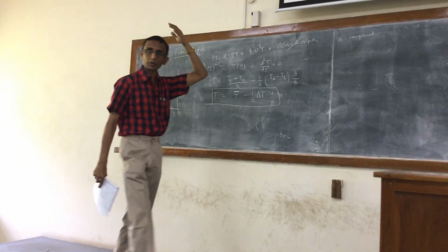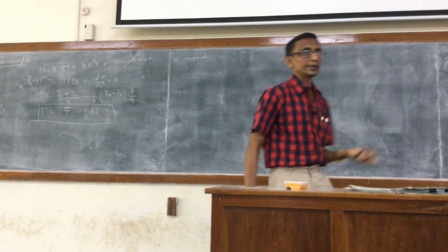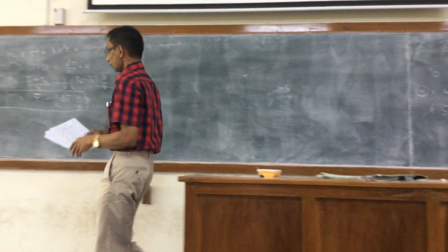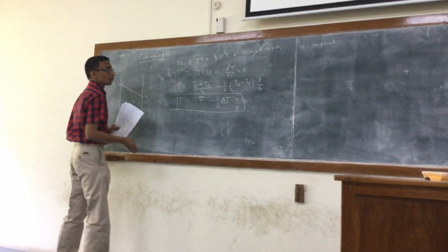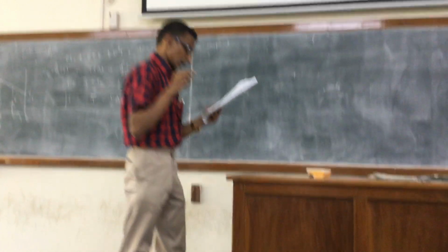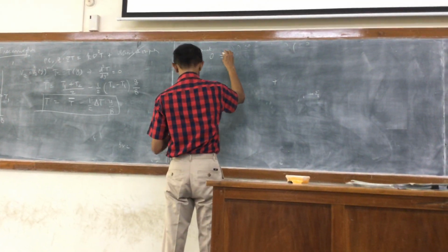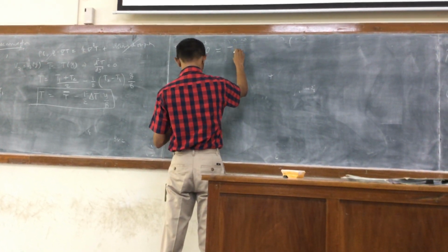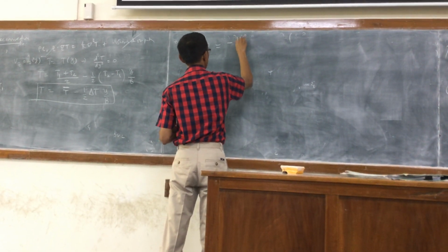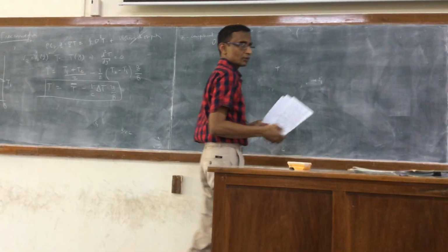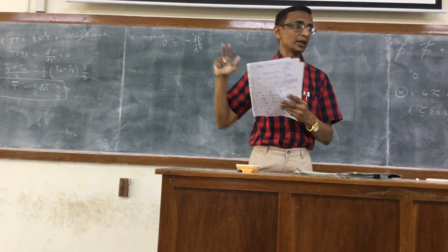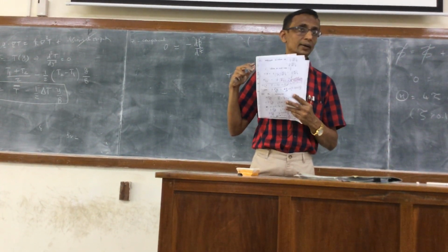So there will be a flow induced by the differential heating of the two plates, right? That is what would happen. So the inertial terms, based on these approximations, you can easily verify will vanish, and so what will be there on the right hand side is minus dP by dz. So you should verify that the pressure variation in the x and y direction probably will be zero. That may be what we get as a net effect of the momentum balance in the x and y direction,